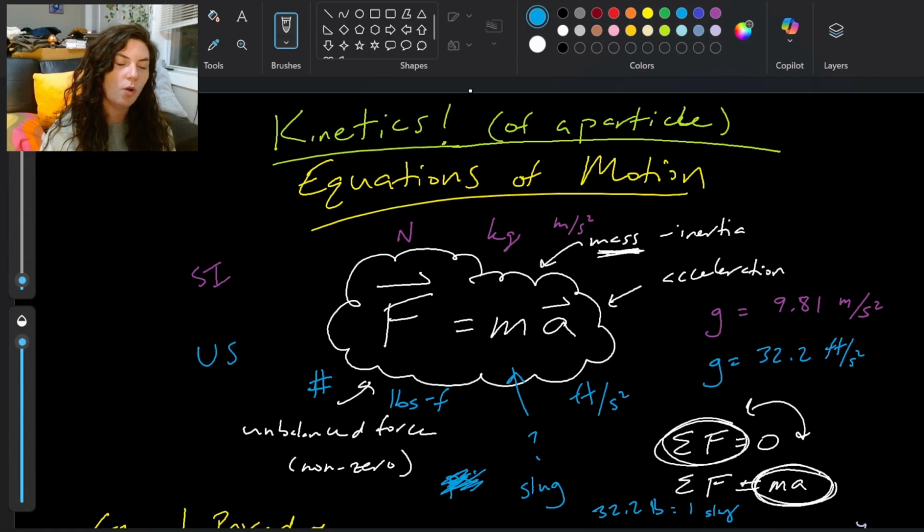The way you almost always see the mass term written out in these equations of motion is that you're pretty much never given anything in slugs. We are always weighing things, we are always working in pounds, pretty much always using the pound force. So for our mass term, we're almost always finding it by taking whatever the thing weighs and dividing by gravity.